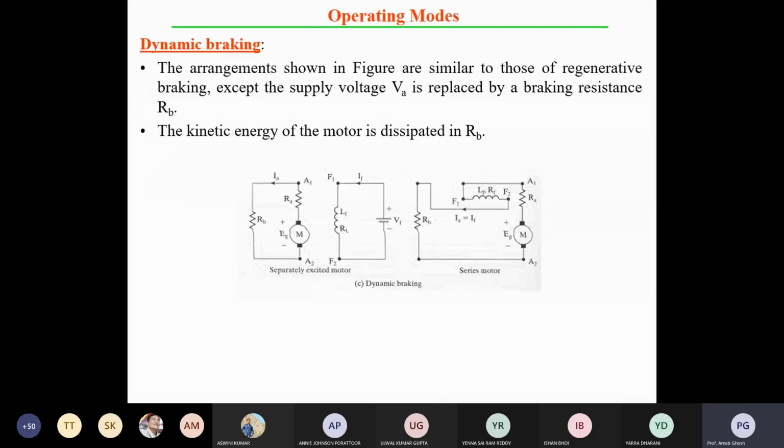Okay, output voltage means load side to source side. It is coming. Okay, but the second stage of that is regenerative braking. So in the coasting period, normally we are doing the regenerative braking. After that, we can switch from regeneration, from the coasting period to the braking period, my deceleration period.